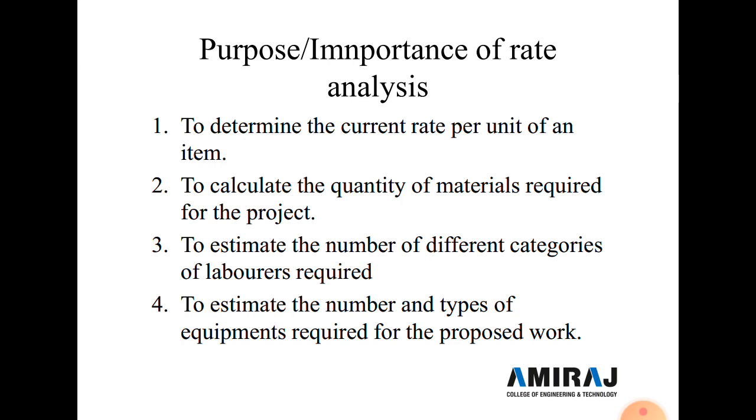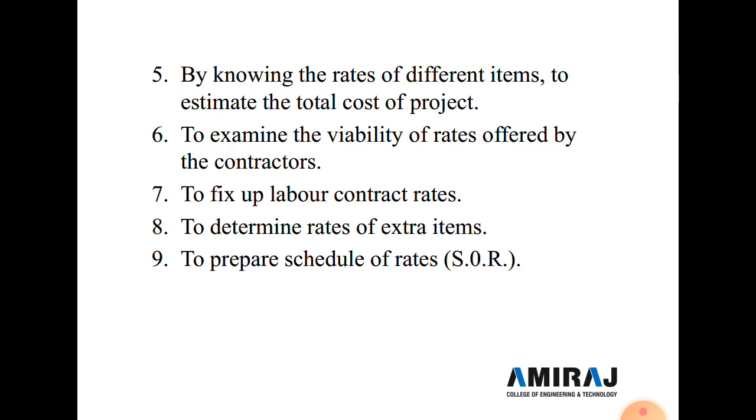So we calculate the quantity of material and the number of labor required in a rate analysis. Then to estimate the number and type of equipment required for the proposed work. And next, by knowing the rate of the different items, to estimate the total cost of the project. So the total budget and total cost of the project are calculated by rate analysis.